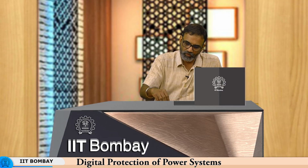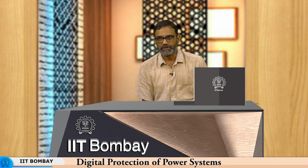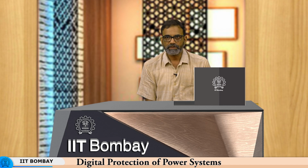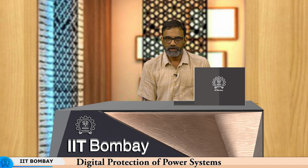So now we will move on to the next level of complexity here. That is the differential protection. The differential protection, as the name suggests, works on a difference principle. That is, the current entering the equipment and leaving the equipment will be different if there is a fault in the system. This can be in terms of magnitude or angle or both.